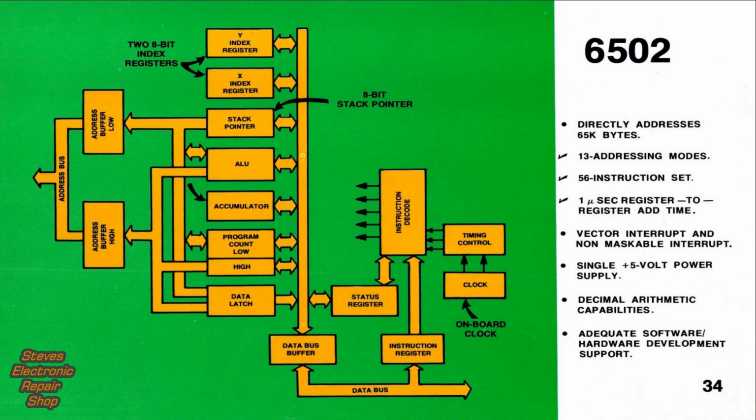There are many models of the so-called 6500 microprocessor. Some contain onboard clocks, and they come in 2 package sizes, 40-pin and 28-pin. Here we see the 6502 chip, a 40-pin package. As pointed out at the bottom right, the 6502 has the onboard clock.